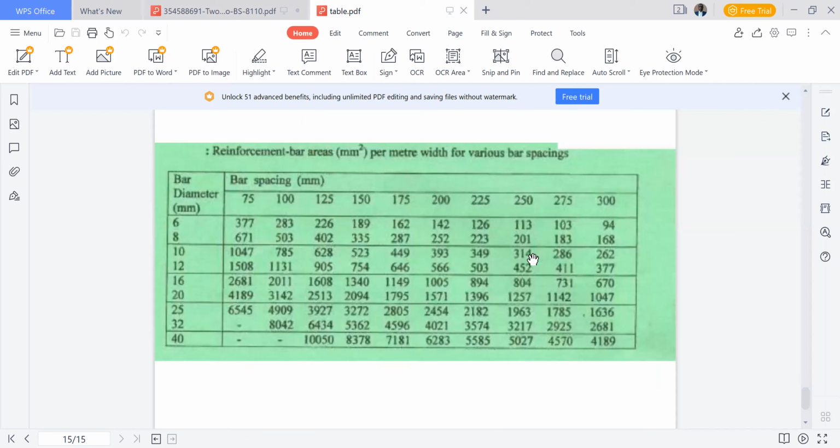The reason I told you sometimes we pick a very high value is because we also need to take care of deflection. During deflection test, the area provided plays a very vital role in making sure that the deflection test is passed. But you should not over-reinforce because it will be uneconomical and it can cause crushing failure because the crushing strength value of concrete will be exceeded before the steel yield. So we took 314, meaning provide T10 at 250 center to center.